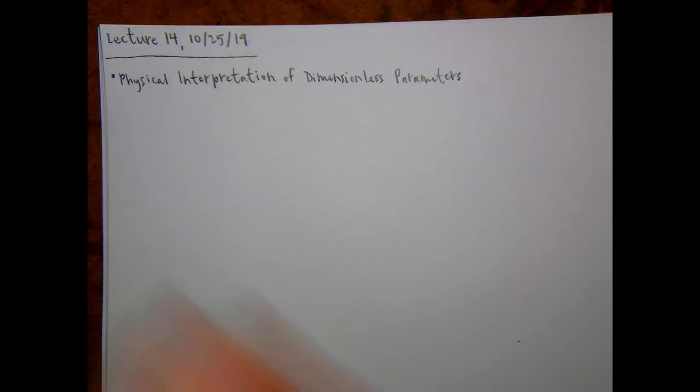Are you all familiar with what I'm talking about when I say dimensionless? It's like there's no units, right? We non-dimensionalized the boundary layer equations by, for example, taking the x position, which has units of meters, and dividing it by some characteristic length, which has units of meters. So you're left with equations that don't have any units, because they're just ratios of one thing to another that have the same units, so it cancels out. That's what dimensionless is.